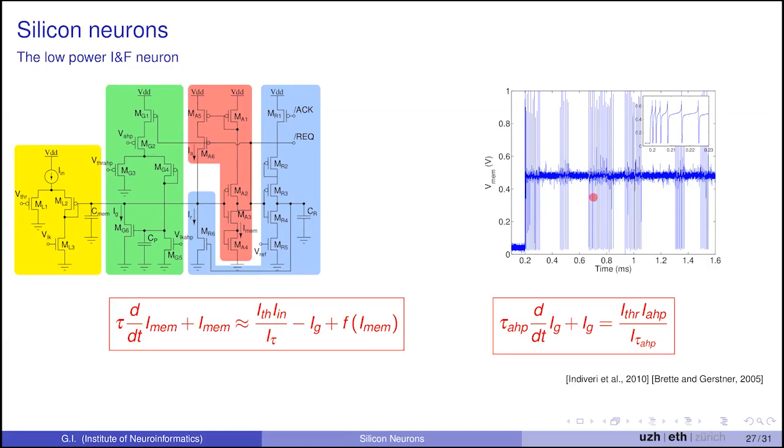And because of the thermal fluctuations, you also don't have deterministic output. You have a stochastic output also in the bursts. So this, again, is a feature or a bug. If you want to model bursting cells, like in the thalamocortical loop of the visual cortex, this is a perfect model of these bursting cells. So it's a feature. But again, if you want to have a closed control loop with very tightly balanced control variables, this is a bug. You should not be using this circuit.